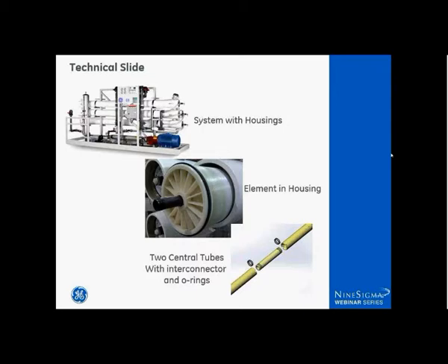And so there are a number of ways that are used to connect pressurized pipe in water treatment. And what we're looking for is a way to eliminate that connector and perhaps integrate the connection into the ends of the central tubes such that we could eliminate a part, reduce the places for leakage, make it easier for customers to install and remove the elements, both when they're new and at the end of life, and to make it compatible with these existing systems, which are very prevalent throughout industry throughout the world.